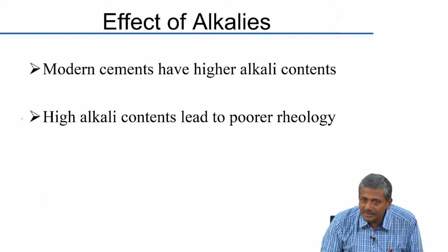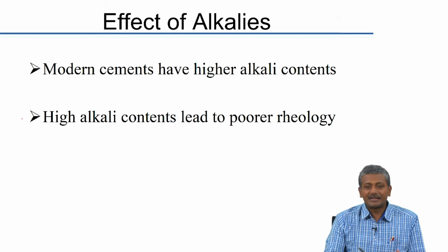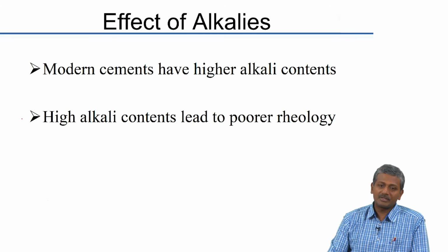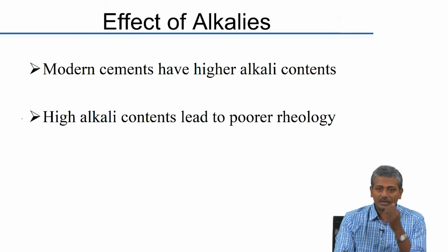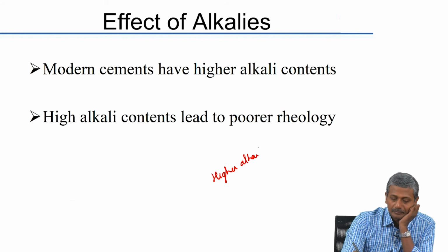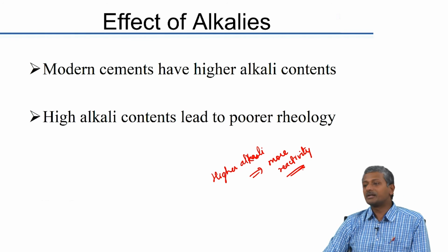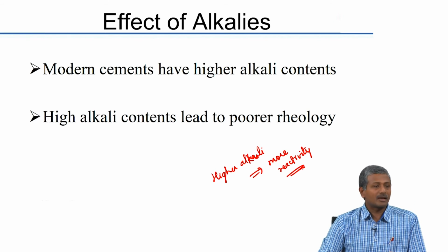Now, alkalis are something that generally lead to a poorer rheology. Okay. Now, modern cements have higher alkali contents. Okay. Now, that is an aside, but even with lower alkali cements the durability is not affected in terms of pH. Okay. Higher alkali contents basically lead to a higher reactivity. Especially when you talk about C3S phases, the higher alkali content can lead to a much greater reactivity, because again you are talking about alkali sulfates mostly, right.